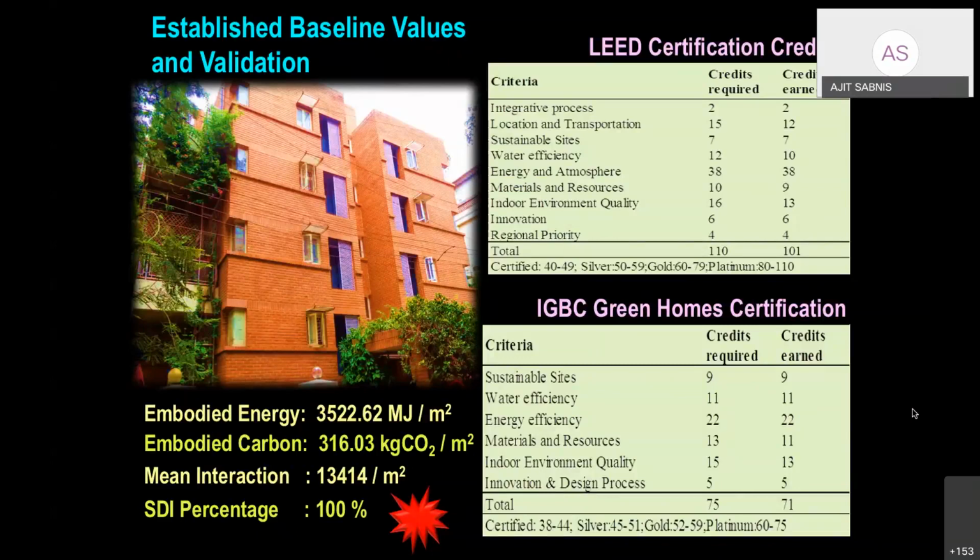Actually, there is a range, irrespective of the building typologies or across the building typologies, it varies, leaving aside the iconic buildings which cannot be normalized or taken into consideration. But the general variation, for example for embodied energy, ranges from 2.5 to 2.75 gigajoules per square meter to almost 8.5 to 9 gigajoules per square meter, across all the building typologies.